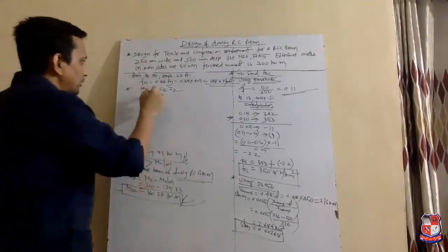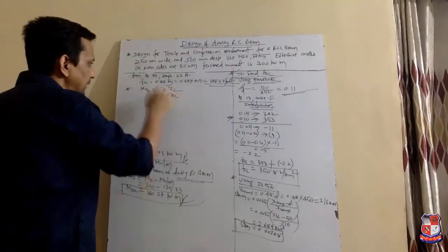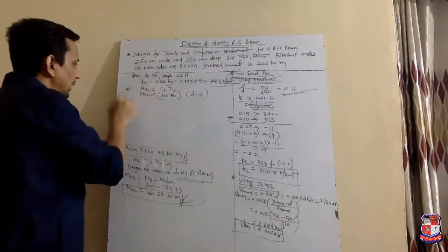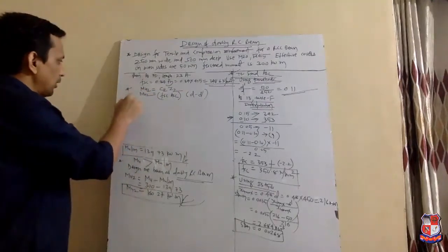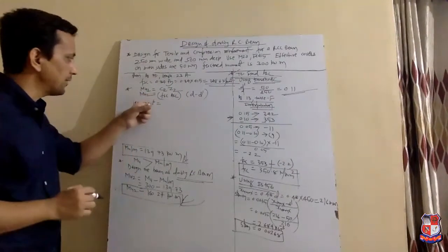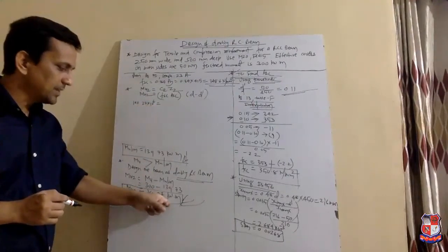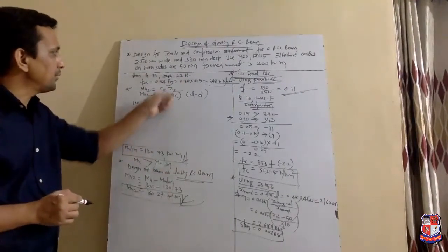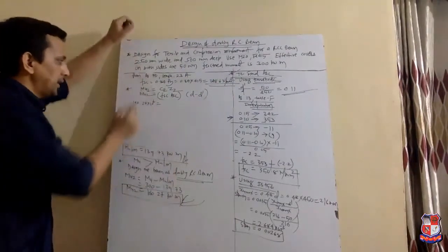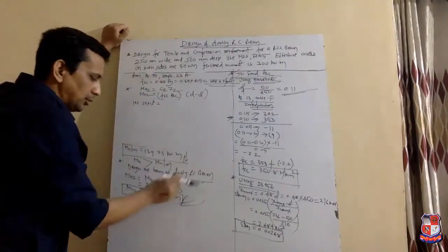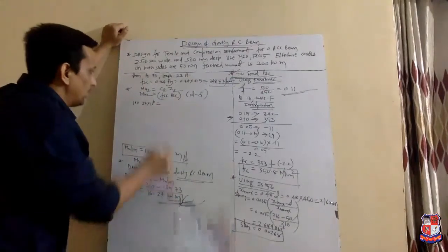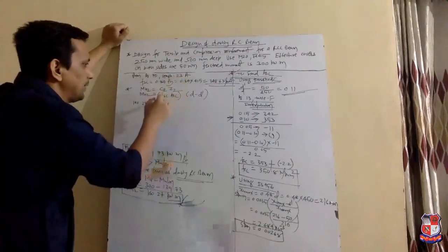And the C2 is equal to, we know, FSC into ASC, and the Z2 is D minus D dash, mu2. And we have the value of mu2, 160.27 into 10⁻⁶. Why have I written 10⁻⁶? Because this value is kilonewton into meter, and the FSC value is in Newton per mm square. That's why I have converted kilonewton into meter to Newton into mm. Kilonewton to Newton is 10³ and meter to mm again 10³. So total 10⁻⁶.